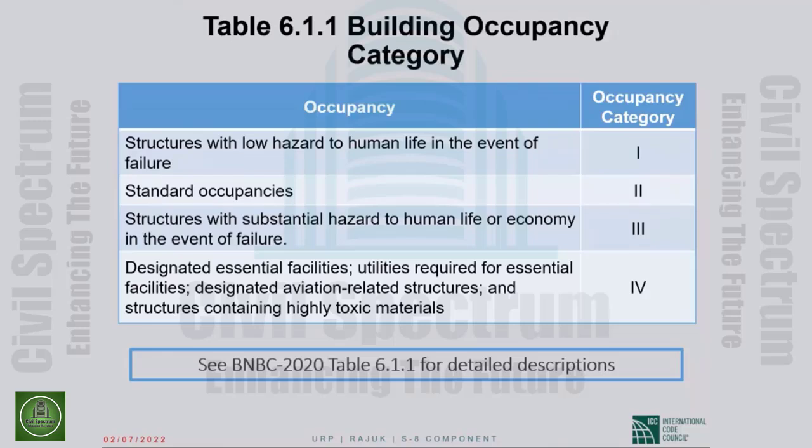That role has now been taken over by the seismic design category, which is a function of the seismic hazard at the site of the structure, which is what the seismic zone was all about, but also the occupancy of the structure, whether it's a hospital or a police station or an office building or a school, and very importantly, the soils at the site of the structure.